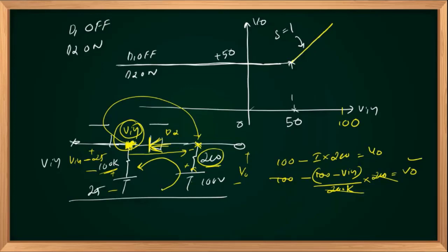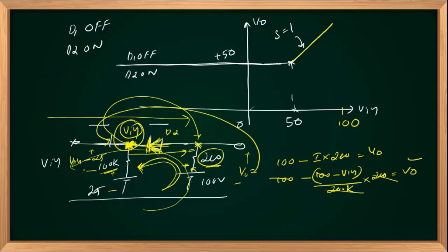Or the circuit current adjusts itself so that this drop is managed so that V out is always equal to this potential. And there is no problem if your diode is connected backward. The only point is that there won't be a current flow in this direction due to the diode connection, cathode to anode. There can be a current flow like this. And that current is fixed by the circuit to ensure V out is always equal to V in. Right? So we could answer our question easily.